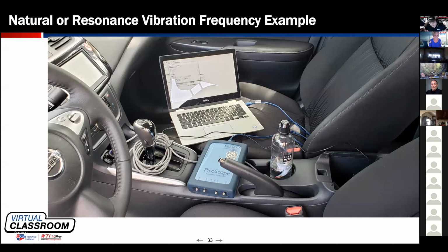Do you realize, if the suspension on that car was designed to be naturally resonant at 20 cycles per second, then that tire, even though always out of balance and maybe shaking on the road, would not transmit that frequency of vibration until it got to 20 cycles per second, or maybe 80 miles an hour or 90.